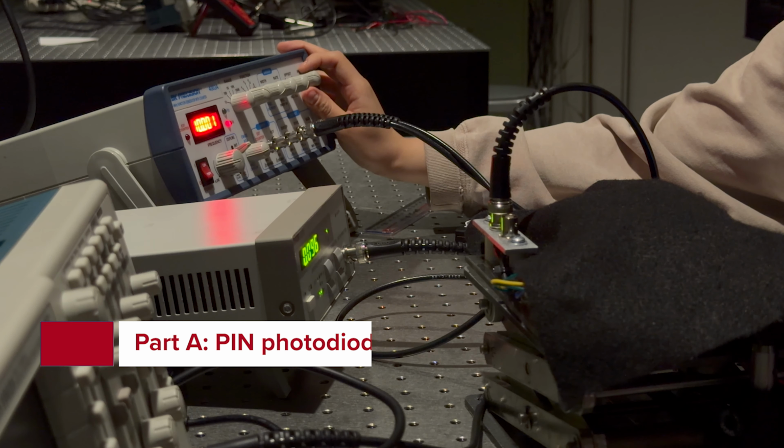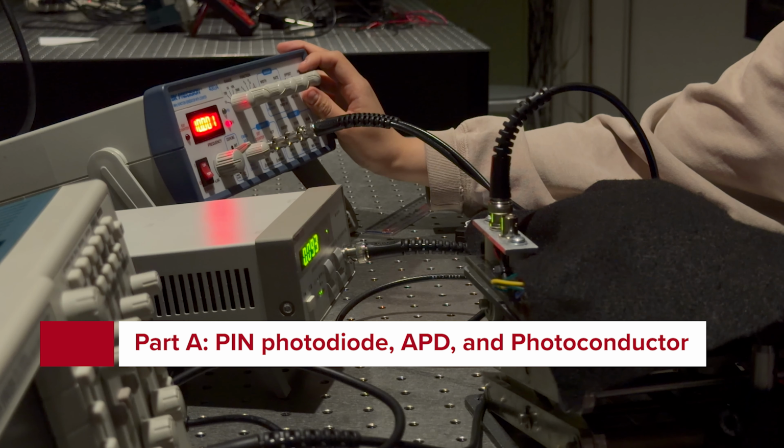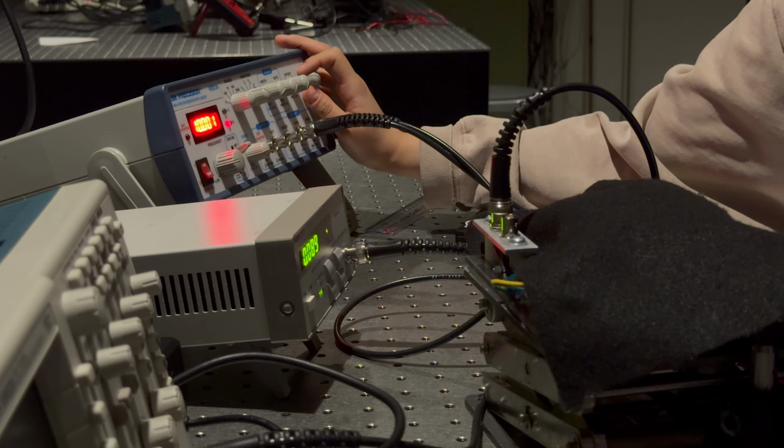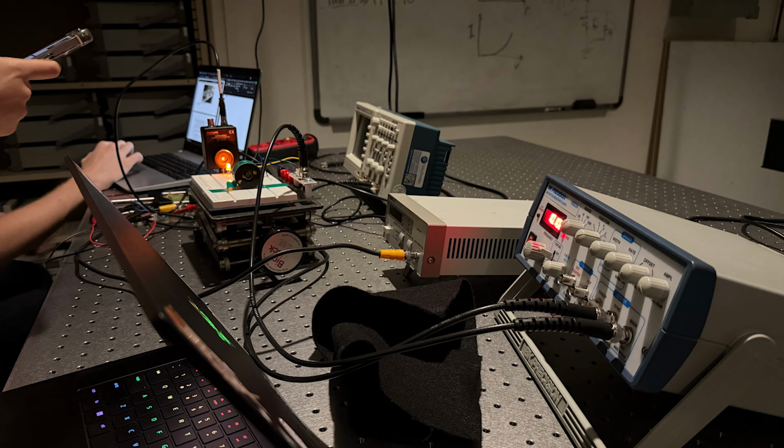In Part A of Lab 11, we compare the responses of a PIN photodiode, an APD, and a photoconductor to the same LED source. They all convert light into an electrical signal, but in different ways, and the 4 procedures demonstrate those differences. We used the LED board, function generator, PD amplifier, oscilloscope, multimeter, APD, pin diodes, CDS photoconductor, strobe setup, and a black cloth to block room light.